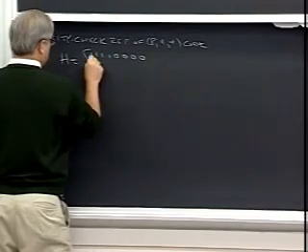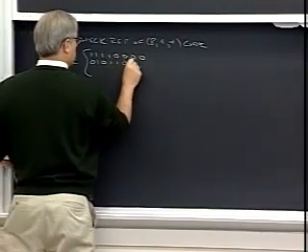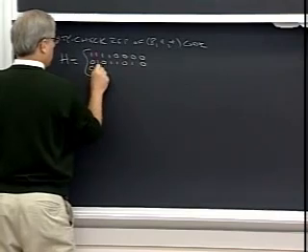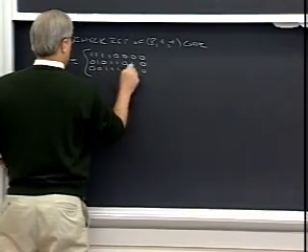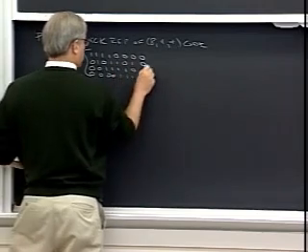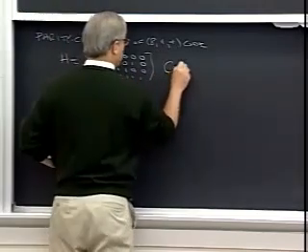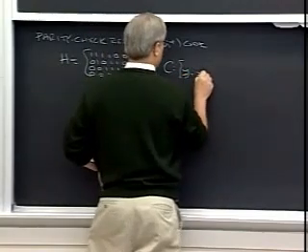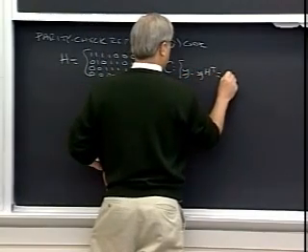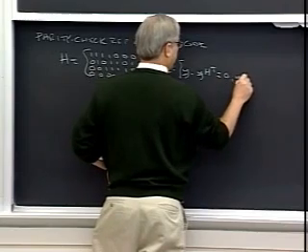And since by now we like trellis-oriented generator matrices, we'll take that one. Okay, so to get very explicit, the code is the set of all y such that yH^T equals 0, where y is an 8-tuple.